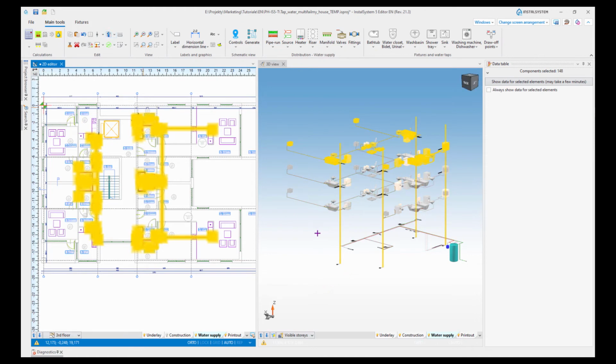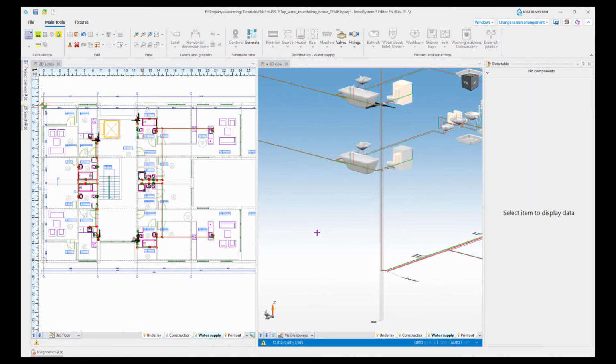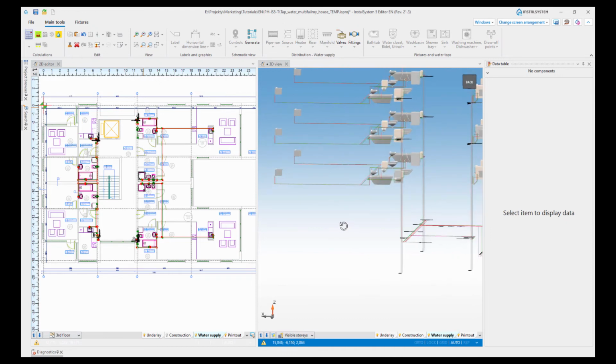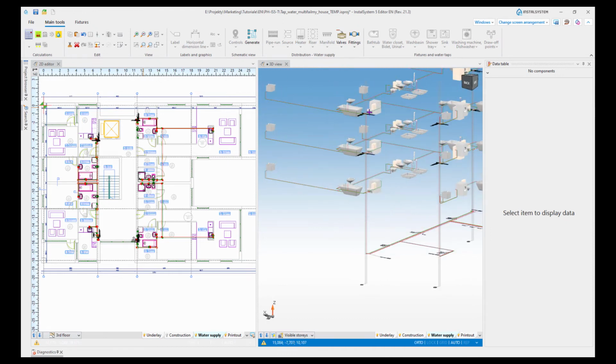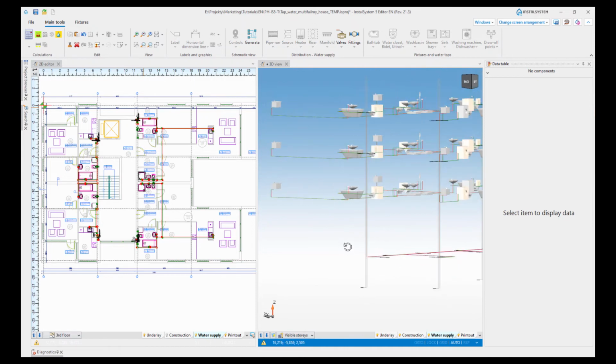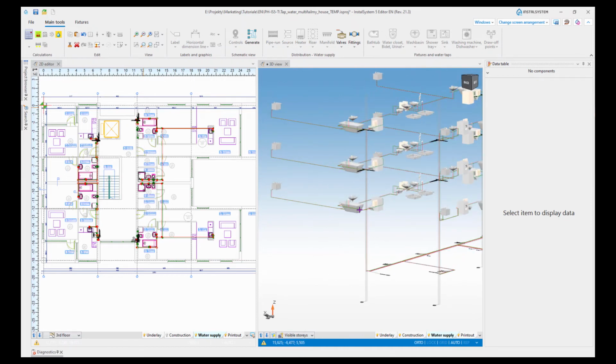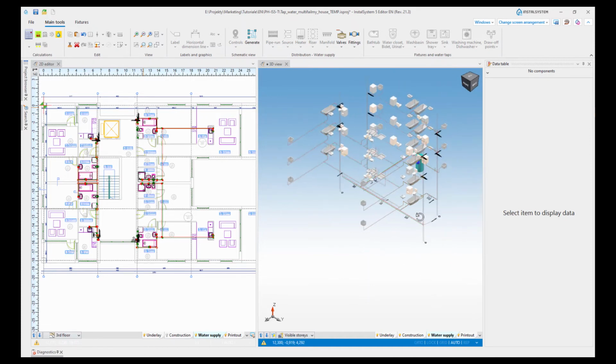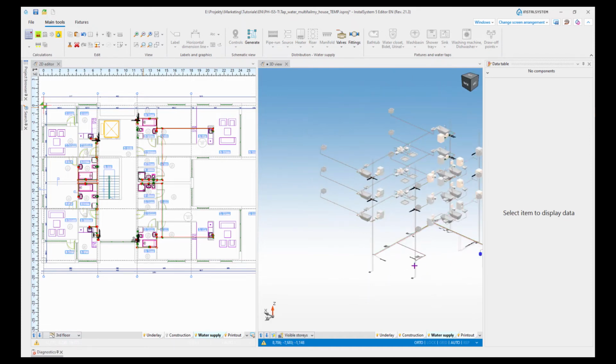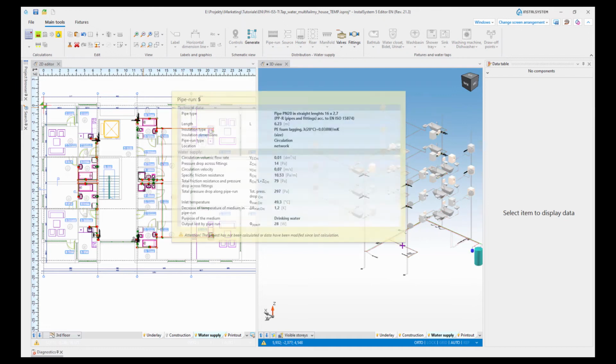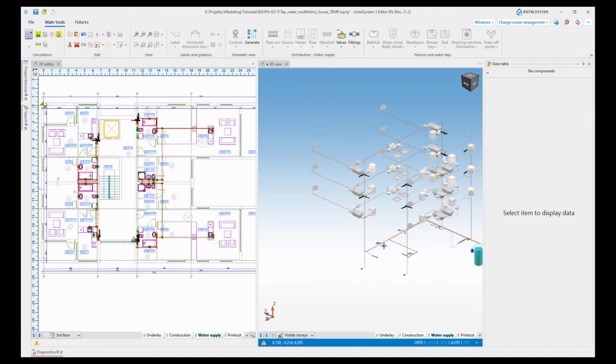And you can see that when we copy the installation, the risers are automatically extended to the right scope, and they cover all stories where the installation has been copied. This is the first, let's say, function, the first possibility of copying the installation.